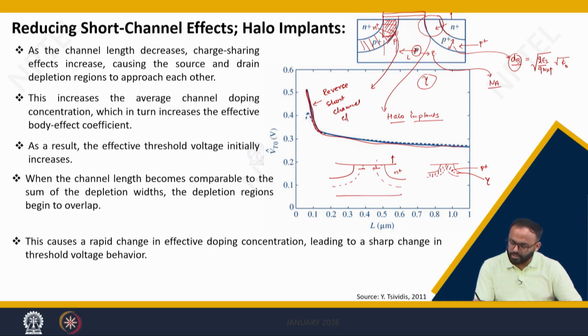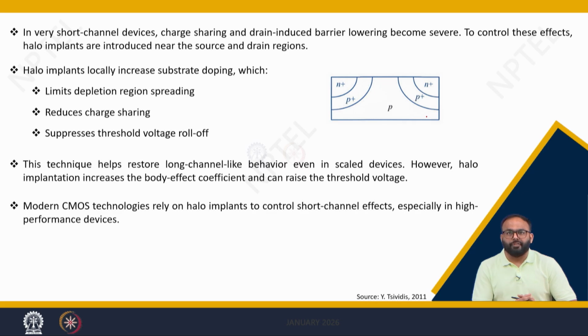Reverse short channel effect. Now, if the depletion region thickness is comparable to the overall channel length, then again there will be a decrease in the threshold voltage. So, halo implants, or including pocket dopings, is one of the possible solutions to reduce the short channel effect, which was introduced by charge sharing.